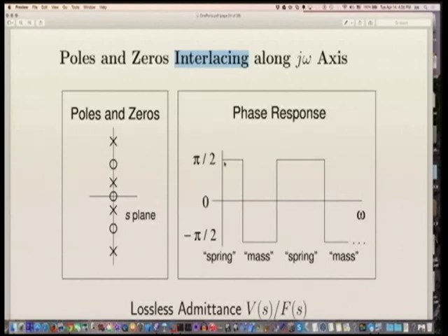The way you normally enforce it is you look at the phase of your measured mobility as a function of frequency and ensure that the phase lies between plus and minus 90 degrees. Usually it'll be offset because you'll have some bad data at low frequencies and you have unwrapped phase. But once you take out the mean in a reasonable frequency range, then you can see it when it's centered about its variation.